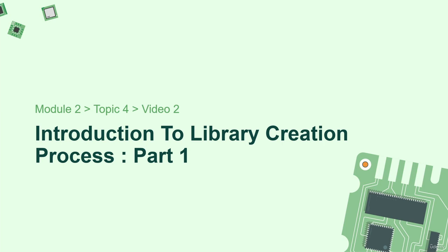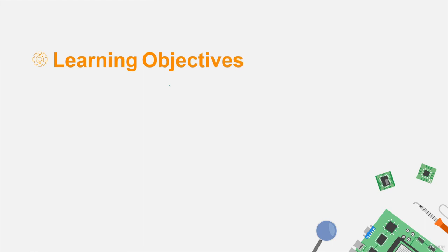Now let's start with this video, which is Introduction to Library Creation Process Part 1. Let me tell you what you will learn in this video. I am going to show you the process to create the library for IC555IC. IC555IC is a very popular IC, and I will show you how to create the library for that particular IC in this video. The first point is symbol creation.